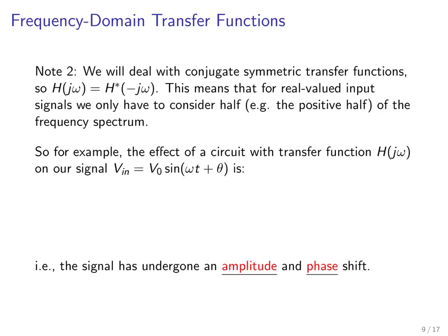Another thing to note is that in this course, and in most cases, we're going to be dealing with conjugate symmetric transfer functions, meaning that the transfer function at a given positive frequency omega is equal to the complex conjugate of that transfer function at its negative frequency, right? So in the previous plot, we showed that a sinusoid has energy at both plus omega and minus omega.